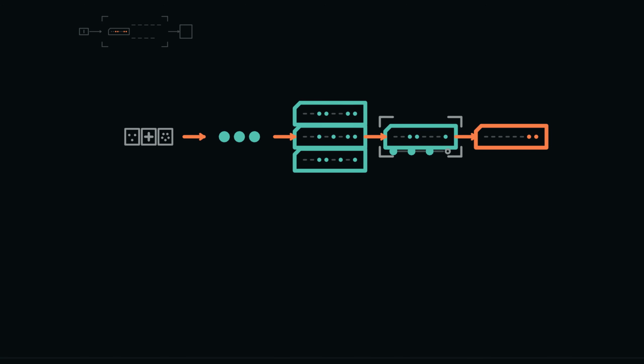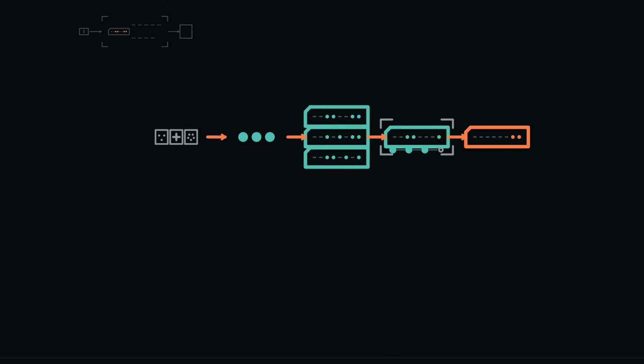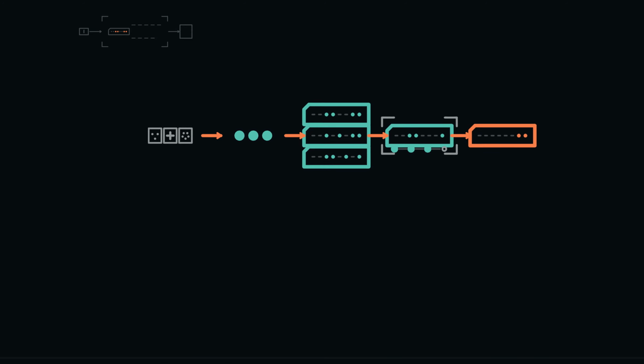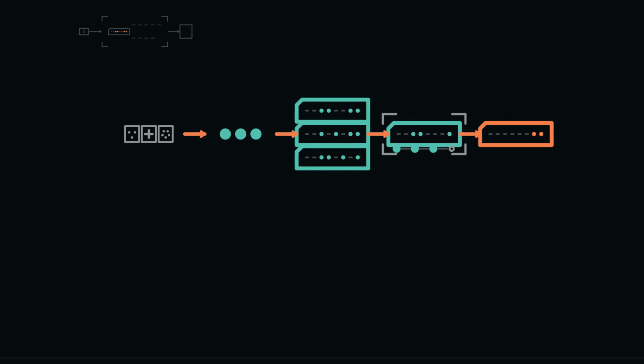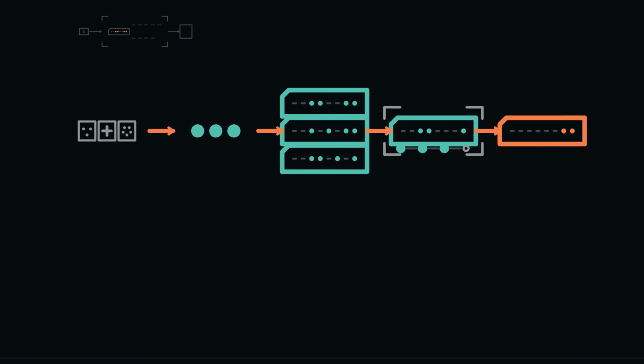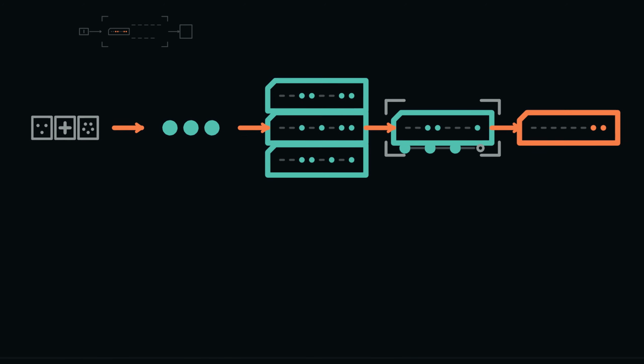The first data load sends address F1 through the ordinary memory path. The keyboard data register returns and consumes hexadecimal 33. R0 captures the same ordered 8-bit pattern. Subtracting hexadecimal 30 produces numeric 3, which R0 preserves while the program waits for the other inputs. Nothing about this operation anticipates 5. It establishes only the first operand from the first key press.